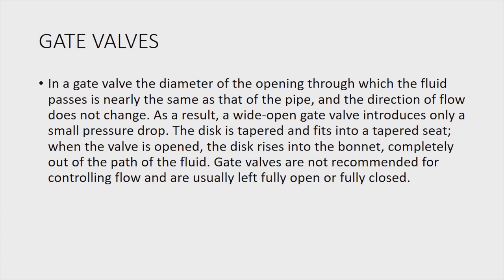Gate valves are not recommended for controlling flow, and are usually left fully open or fully closed. So these are a type of valves which are left fully open or fully closed. You can note the example of a gate valve.